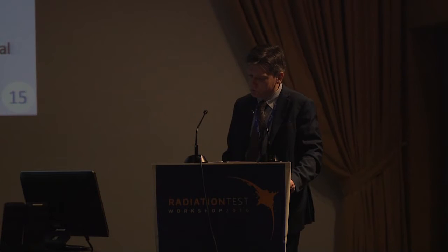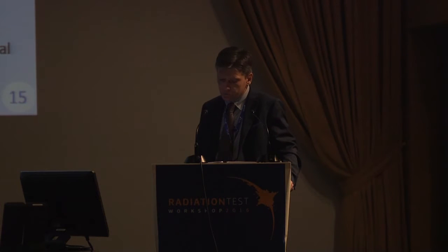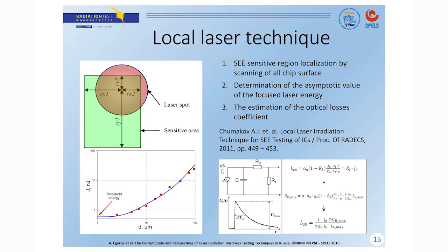Local irradiation means laser irradiation of a comparatively small IC region with variable spot size from several microns to hundreds of microns. The spot size is varied by shifting the device away from the focus point of the laser beam.